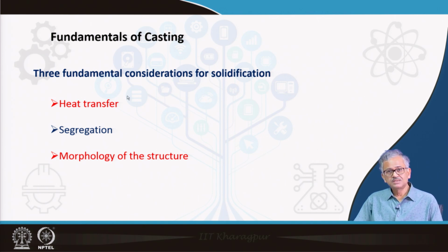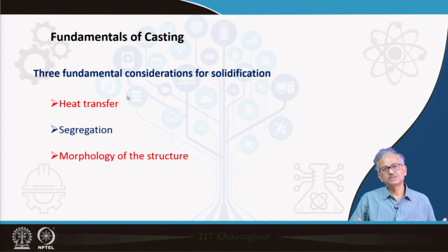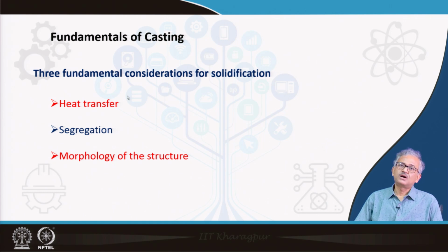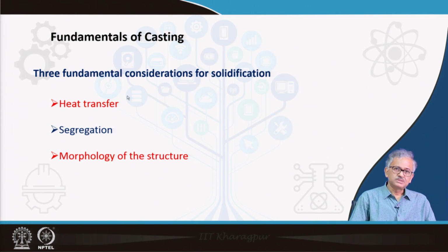And then segregation is very important, because impurity segregation takes place during solidification, as we all know, and we will discuss how to measure this segregation, that is, the quantification of this segregation. That is, what the impurity concentration in the liquid is and how it evolves with time as well as solidification. We will give that quantification. Since we will develop the model, based on that we can know what the parameters are that influence the segregation and how to eliminate the segregation as much as possible.